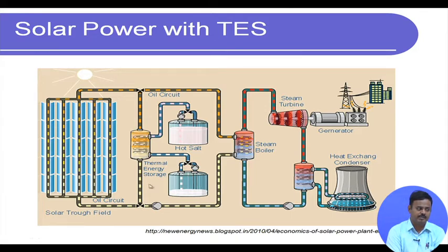during night time or during a cloudy day. The oil will move up like this and gain heat from this heated molten salt, and then the cooled down salt will accumulate in the lower reservoir. The heated oil then will go through this circuit, go to the boiler, generate steam so that the power generation is maintained, and then come back and just complete the loop like this.